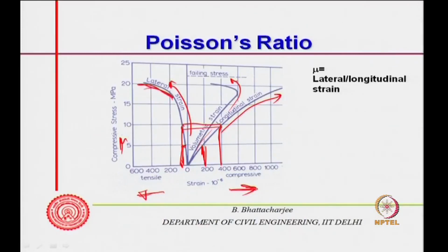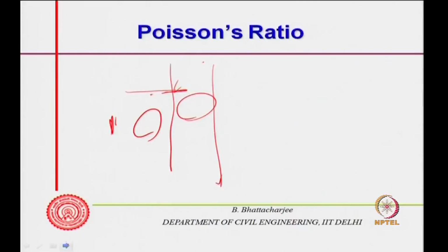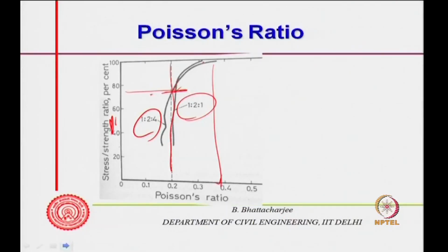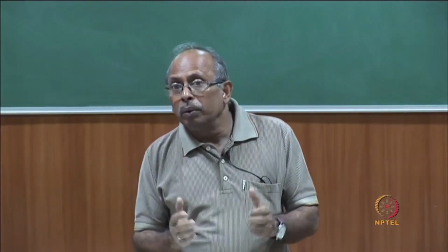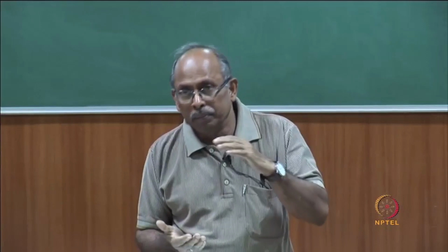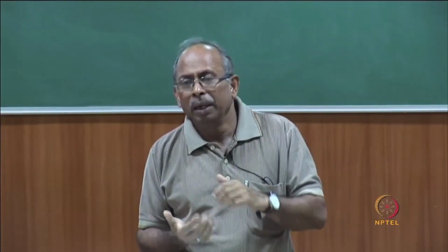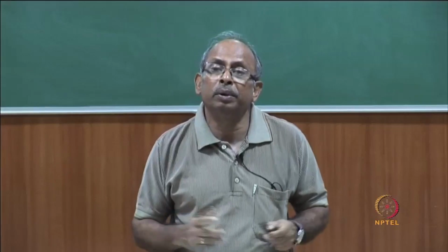Suddenly the lateral strain is increasing; here it was increasing in a slow manner, but it started increasing in a faster manner. This one is almost close to linear, with slight variations, but this increases at a fast rate, and this increases still at a faster rate. We can understand this from the physical scenario, because micro cracking would result in a lot of transverse deformation. Longitudinal deformation also would be there, but lateral deformation will increase significantly because of the micro cracking.